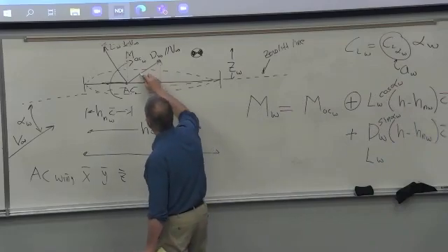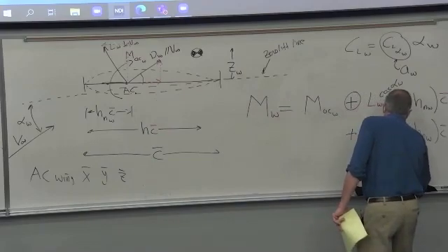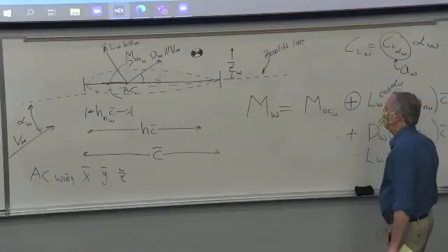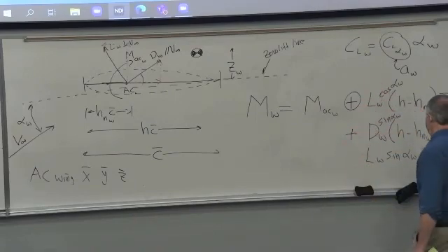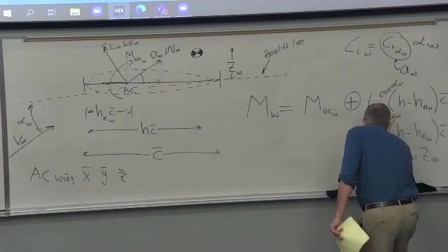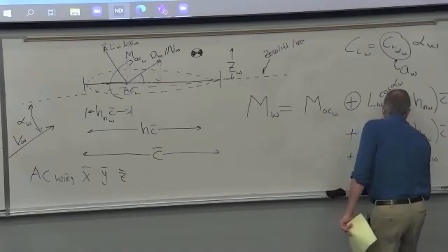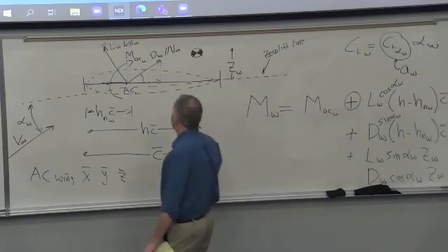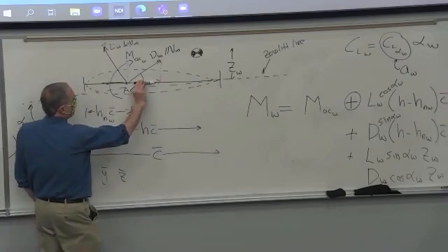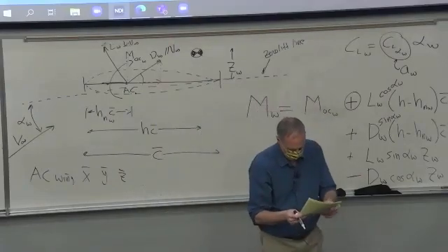And then that drag component is sine, right? Because we're doing this one. So this is the angle here. And here we got the lift of the wing times the sine of alpha wing. And our moment arm is ZW. Is that positive or negative? Looks like it's down here, acting that way, so it's positive. And then we got the drag of the wing, cosine alpha wing times ZW. And is that positive or negative? We're talking about that vector. It's below the CG, goes down. That's a negative. Let me double check, make sure I didn't get my signs messed up.